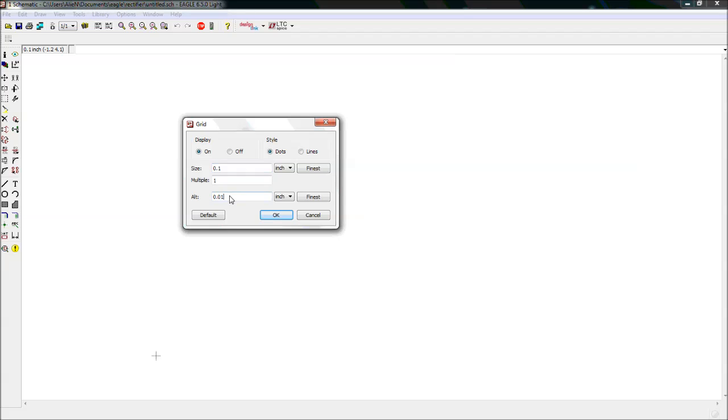Then why are we using this grid? Because generally all components are in sizes of inches. They are in multiples of inches. These are the standards. Maximally they are of 0.1 inches. The distance between two terminals is 0.1 inches, and sizes are in multiples of inches.